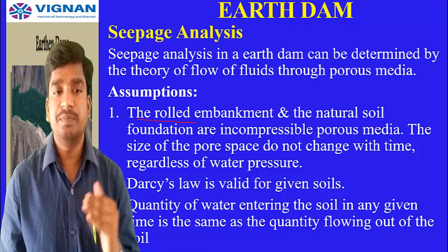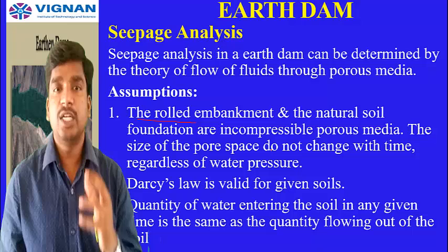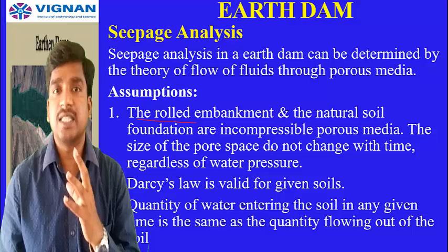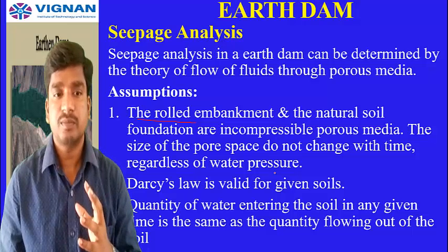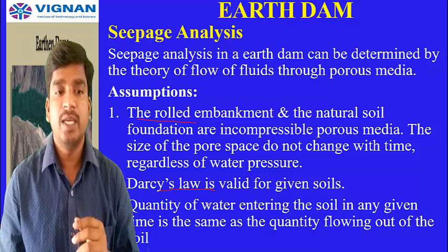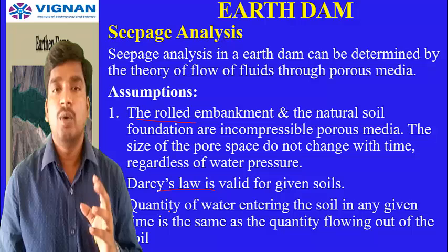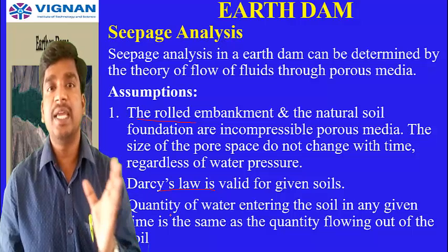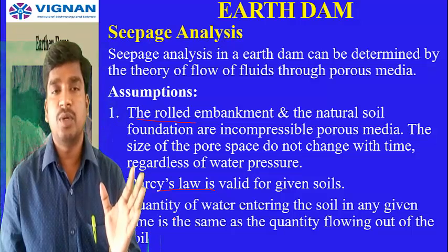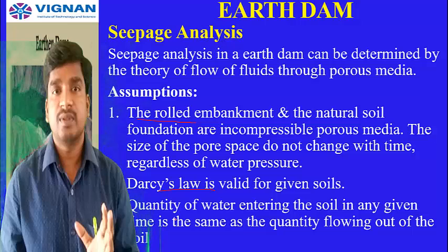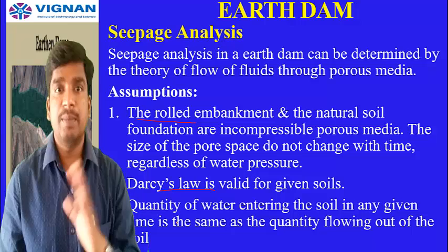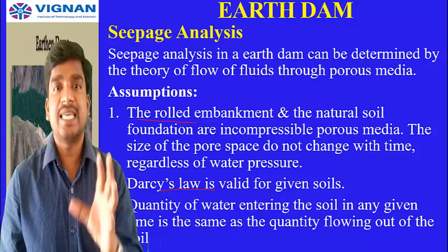Now moving on to the second important point: it obeys Darcy's law. Whatever analysis we are taking obeys Darcy's law. For a given soil, Darcy's law is valid. Now the third important point is that the amount of water entering into the dam, meaning seepage, and the amount of water going out of the dam are the same.